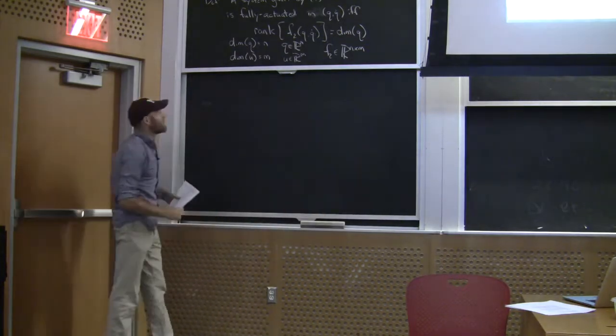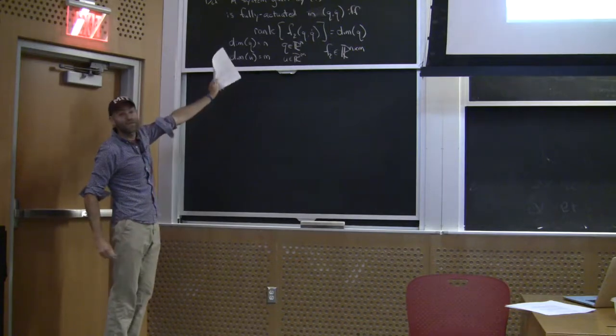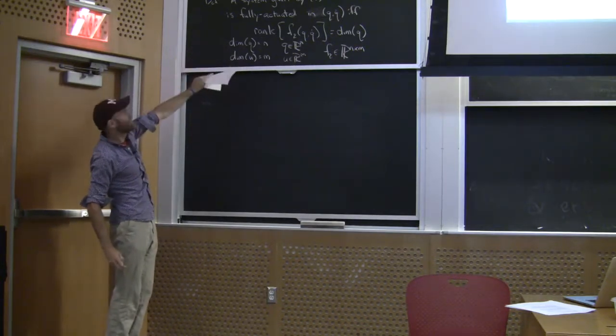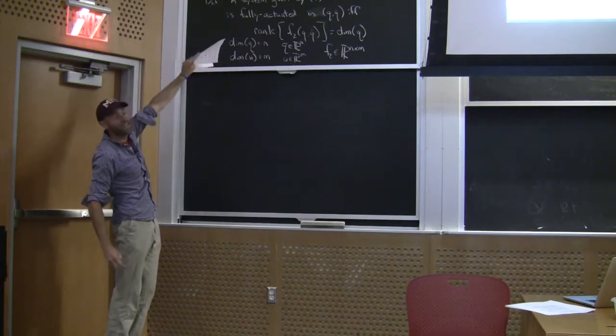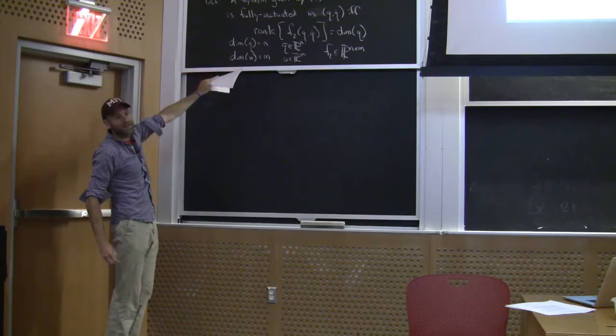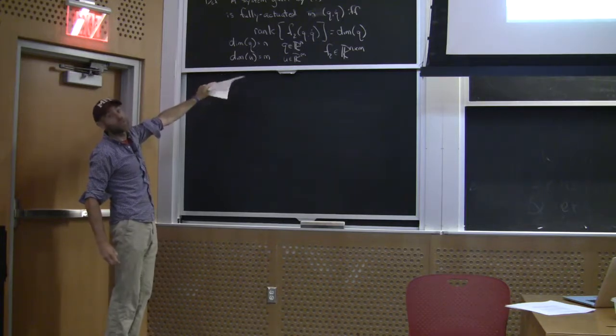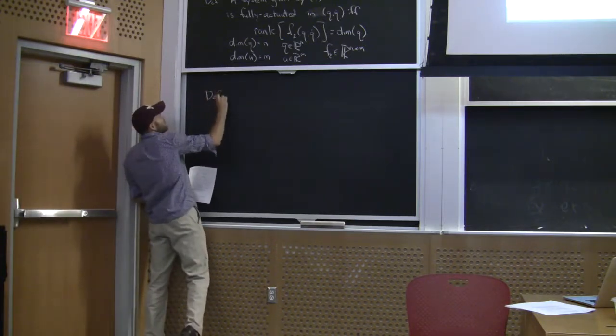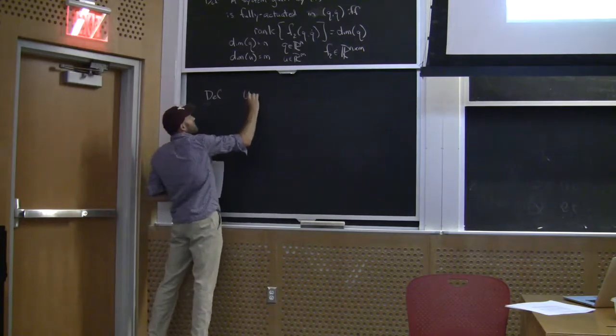Basically, if I can take an inverse of F2, then my claim is if your robot has dynamics of the form where you can take an inverse of F2, then your robot is simple to control. If you can't take an inverse of F2, it's really hard to control, or it's harder. That's what we're going to talk about here, right? So, of underactuated system.